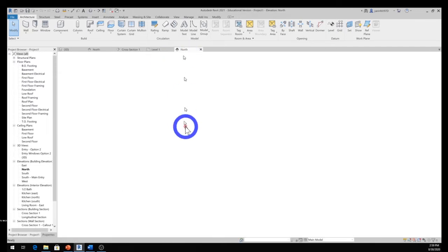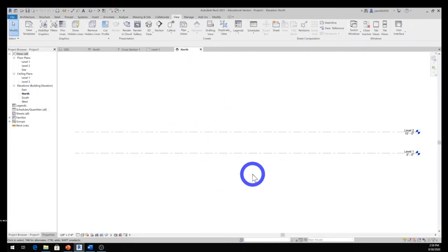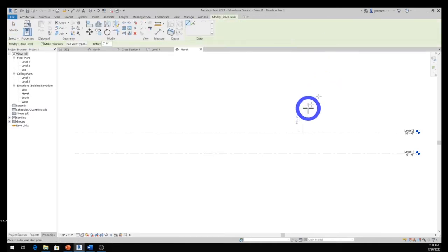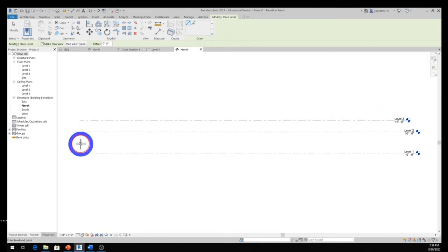That wasn't it. We were right here. So let's go ahead and make more elevations. You go on top of your ribbon. You can see where it says Architect. Click on that, and then you go all the way far to the right. You see something called Level. So click on Level, and then come down here, and let's end up with a bunch of them. Just a few in here. There's one right there, and we're going to put the grade on it later on.